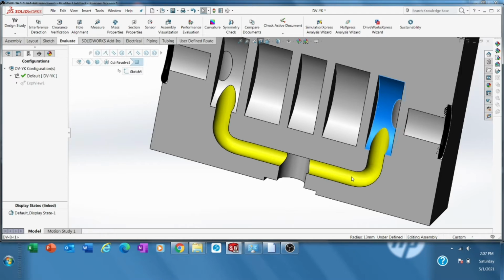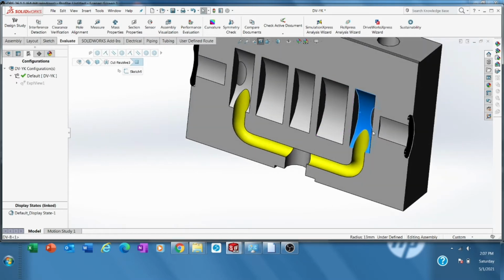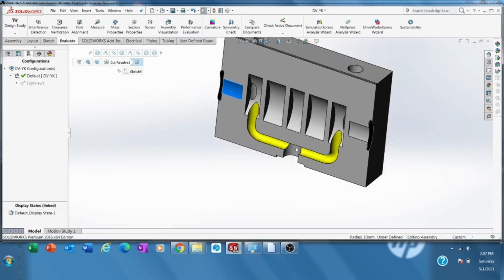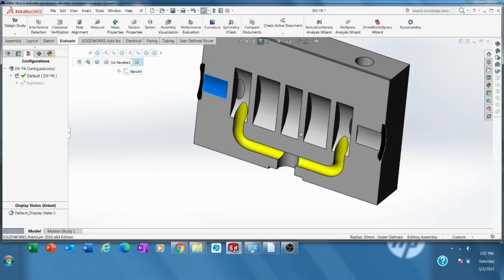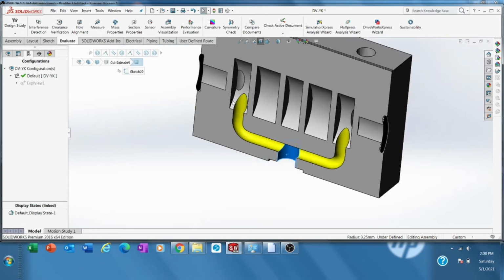It means the spool at the center, this spool, as I mentioned before, is balanced left and right, so there is no possibility this spool moves to the left or to the right. When the pump pressurizes, let's say 10 bars to the left, 10 bars to the right, there is no spool movement. It will be kept at the center, because the force from the left and the right is equal, and the sum of the force is 0. There will be no movement at all. Maybe there is a small movement but it does not affect the system. So the P port is connected to this area.